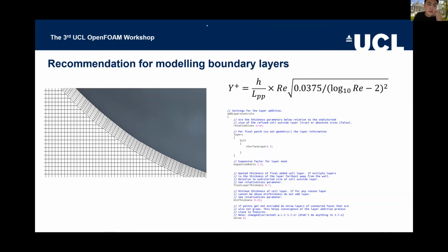In this boundary layer problem, this is a ship hull, and this is normally the hex mesh we use outside the hull, and there are many layers here. These layers should gradually increase from this to here, and this leads to several questions. What should be the total thickness? What should be the first layer thickness? What is the expansion ratio of the mesh from layer to layer?